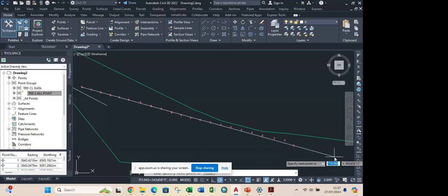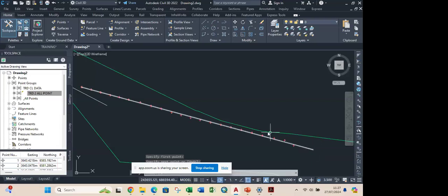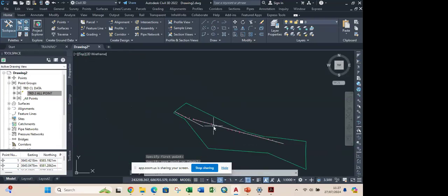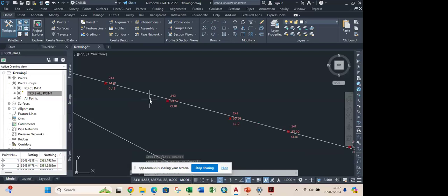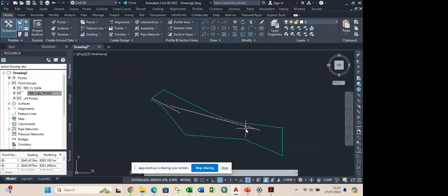Say it's a straight road. Why would I put multiple curves here? I'll go back. Let me just put this here. I'll put it here. This is now the straight. So you can see for most of the curves, the line didn't touch them, but at least one or two, once the line passes them, you're okay with it. You just plot your line like that and go. Then you go to the next. If you're having a longer stretch, you do them individually to get the road alignment perfectly well.